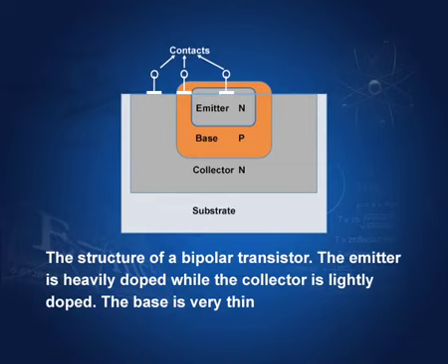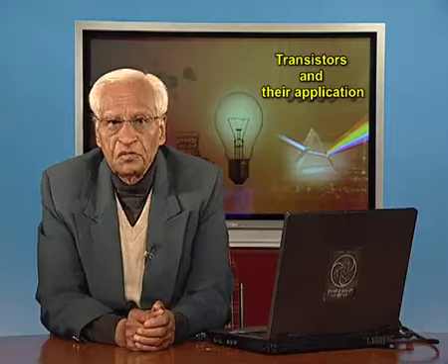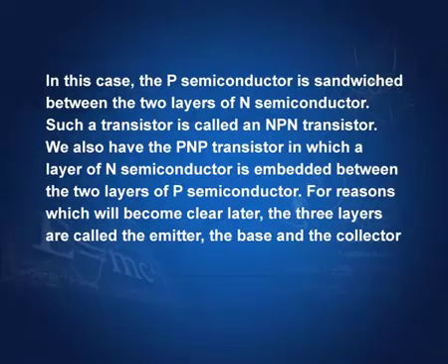We could have p, n and p also. This is an n-p-n transistor; we could have p here, n here and p here. So, we would have a p-n-p transistor. The overall structure would be similar: the base would be very thin, and emitter and collector would have different amounts of doping. Emitter is highly doped, collector is slightly doped to make it conducting.